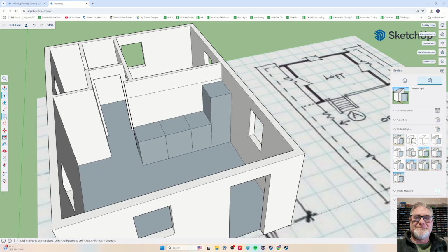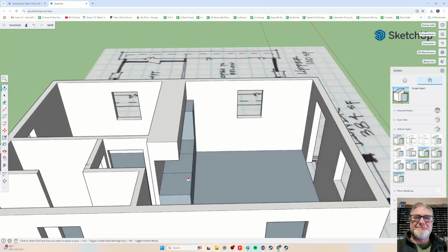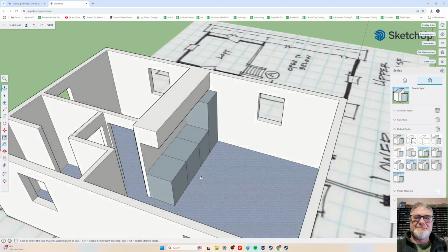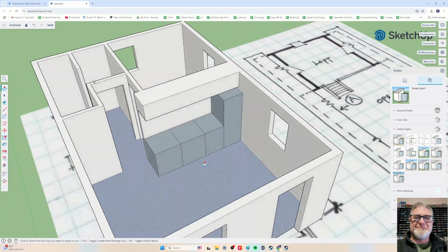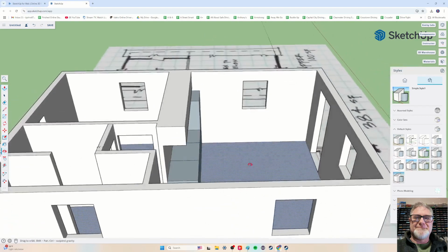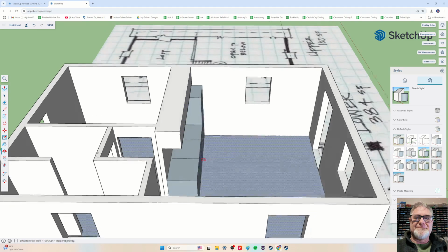And then here, we want to push-pull the cabinets out. They are typically not the same depth as the countertops. They're just back a little bit. How much? Again, we could be official, but for this, just less. Sometimes people say they're about half. So if you want to shoot for that, that's fine. Anywhere in there is fine.